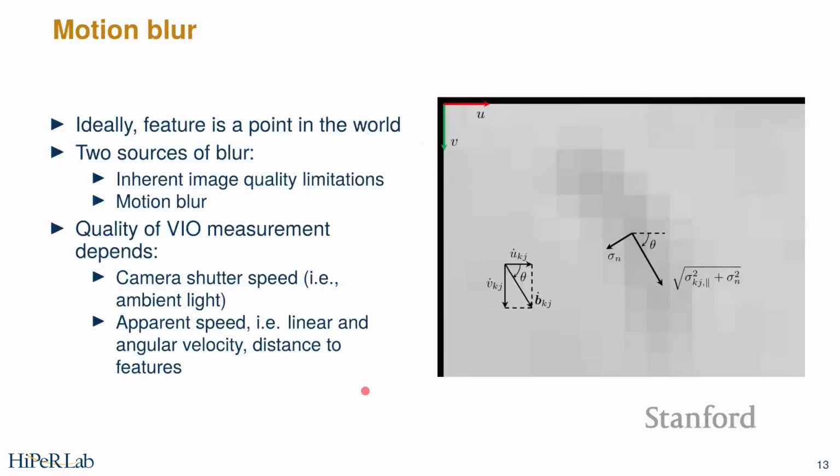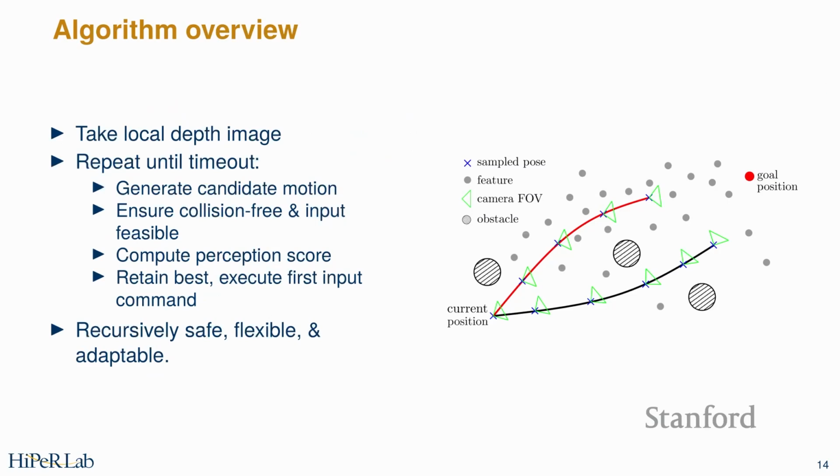Yeah, so let me just stick to this cartoon here. What we do is we assume that this depth image is pristine, so there's no uncertainty in the depth image. We assume the world is stationary, and we take our robot and model it as a sphere, which is the size of the robot plus a little bit of safety bound.